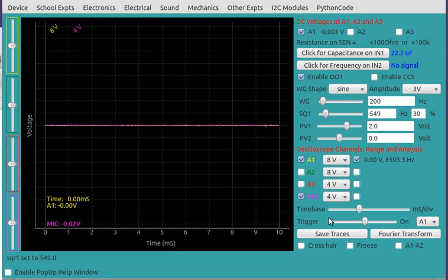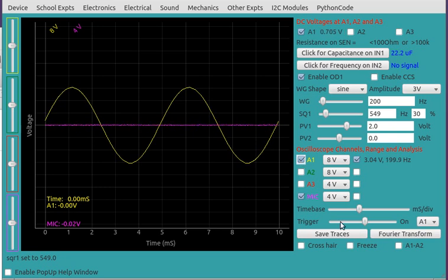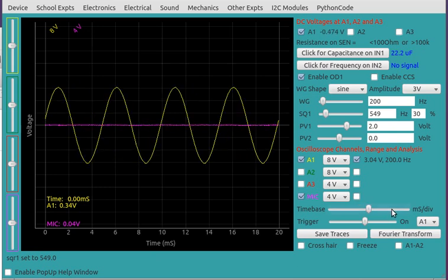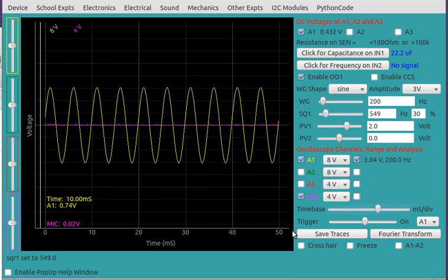And now the time base we already explained. I mean, if you change the time base, what will happen? Like suppose say connect the sine wave again back to here, and time base decides the size of the x-axis. So if I want to see more cycles, I change this timing. And then the other one is the trigger level.